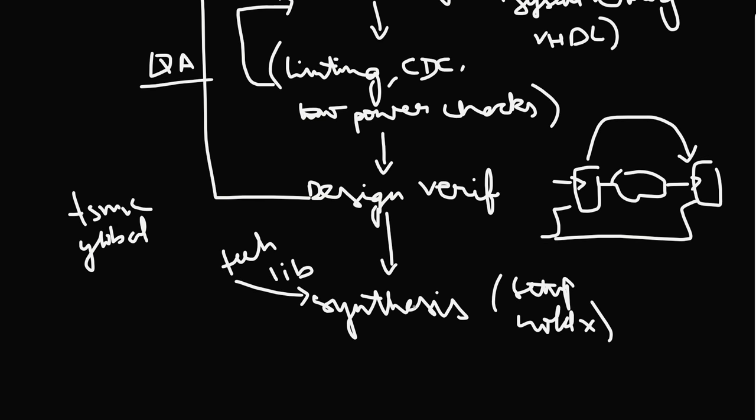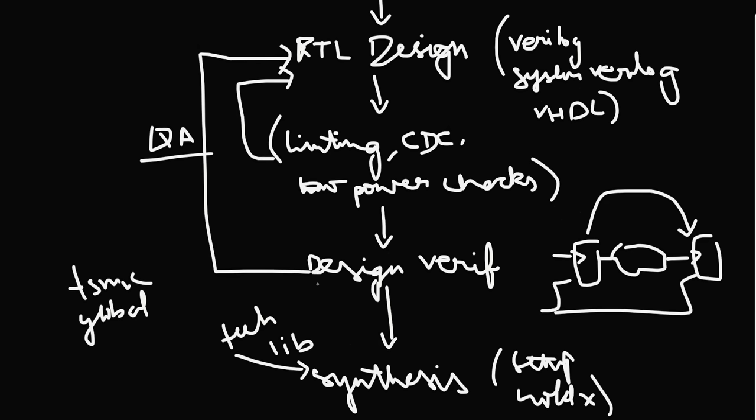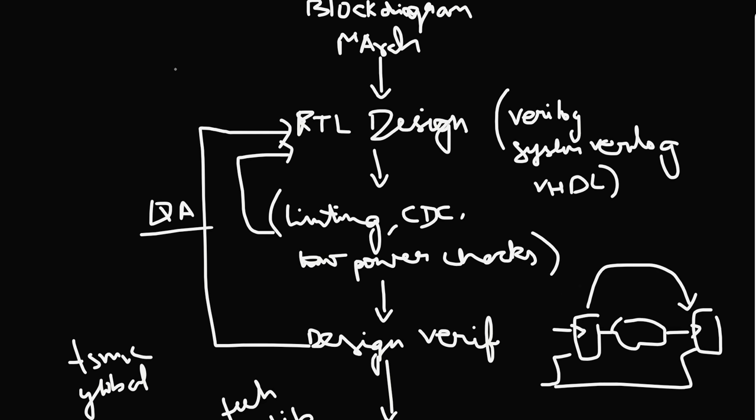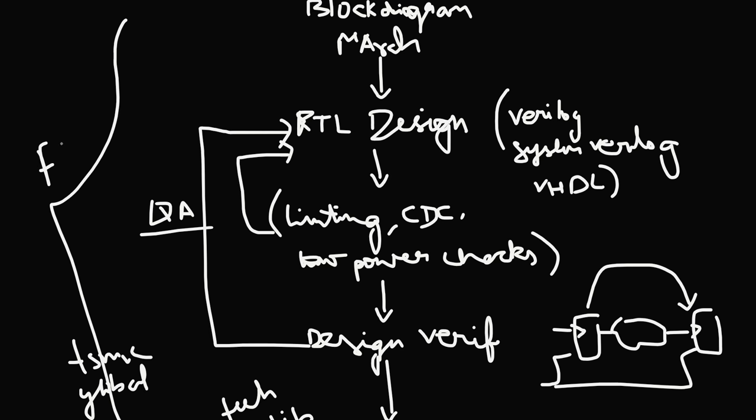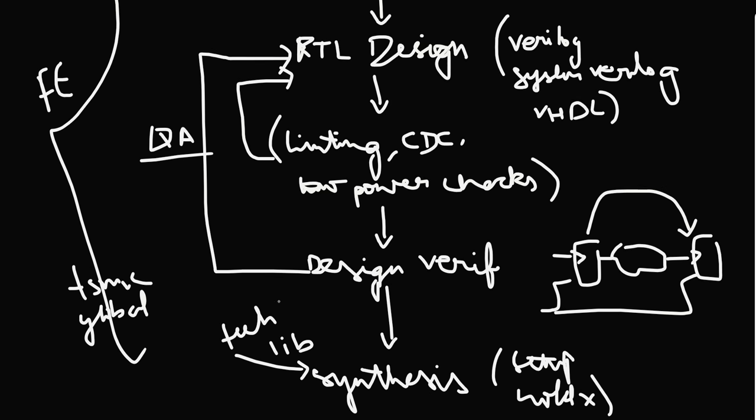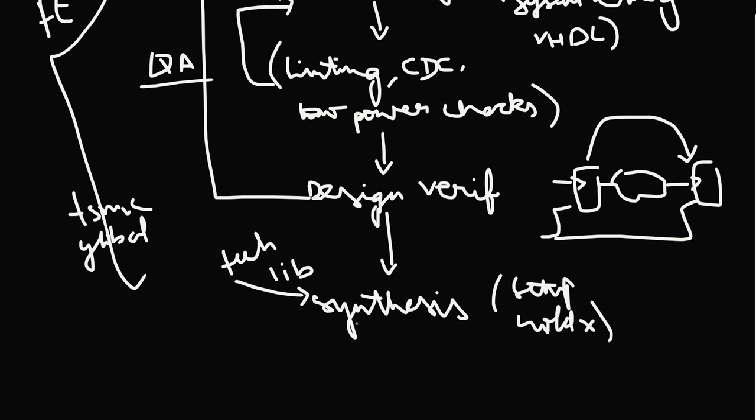So these are the three things which happen in this. One is conversion of the complete design into a gate-level netlist, and then we do the timing closure. Mainly the setup violation is closed, any setup checks are closed, and then we also map all these different gates and cells to the technology library cells. So this forms the front end part of the VLSI flow, right from the spec or the RTL design to the synthesis stage. Synthesis is somewhere in between the front end and back end.